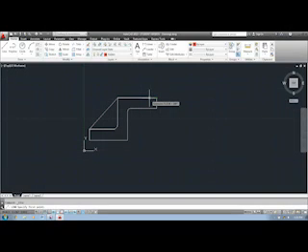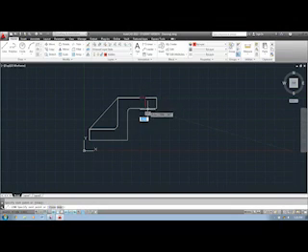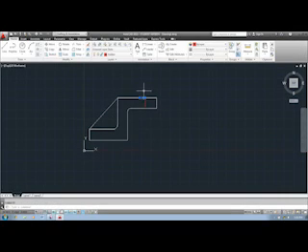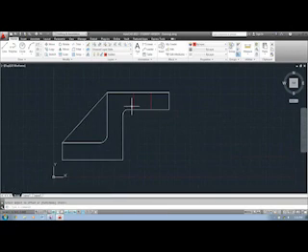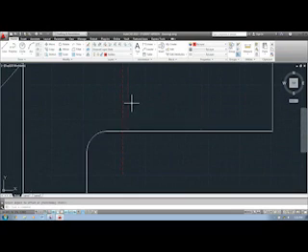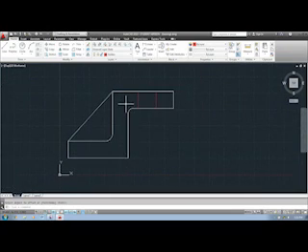And let's see, 7.5 this way, straight down. Okay, I'm going to use the offset command again. This distance is going to be 15. Just select this line, put it over here. There we go. I'll need to change my line type scaling of it eventually, but not going to worry about that just yet.